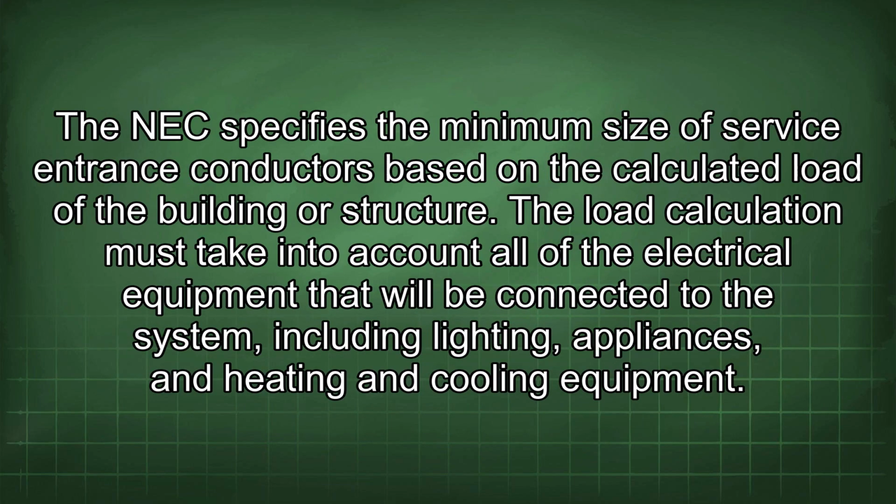The NEC specifies the minimum size of service entrance conductors based on the calculated load of the building or structure. The load calculation must take into account all of the electrical equipment that will be connected to the system, including lighting, appliances, and heating and cooling equipment.